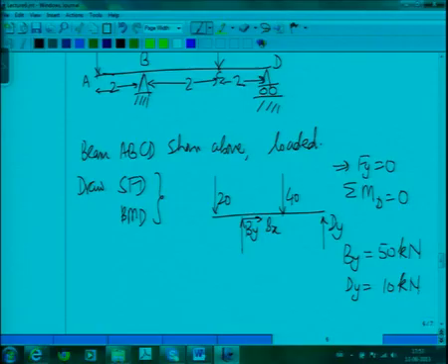You carry out the moment analysis. So, take Bx is obviously 0 and you take moments about one of these points. So, sum of these is equal to 60, one of them is 50, the other is 10. This comes from moment balance. Okay. So, this you will get, I think there is no big deal.